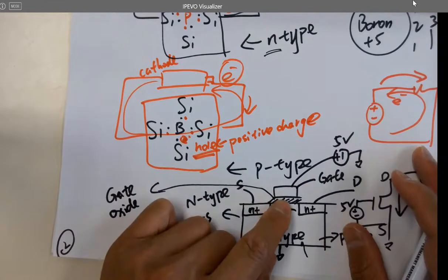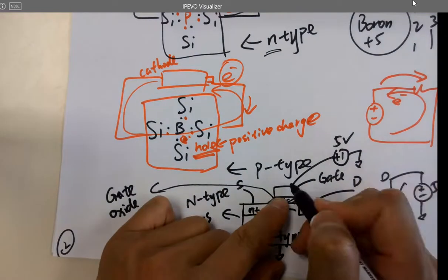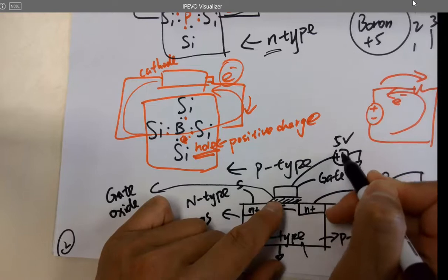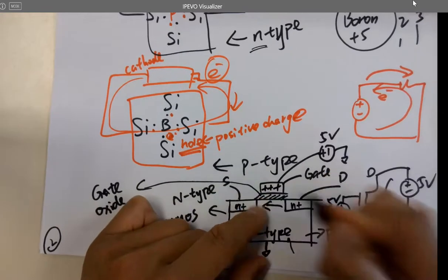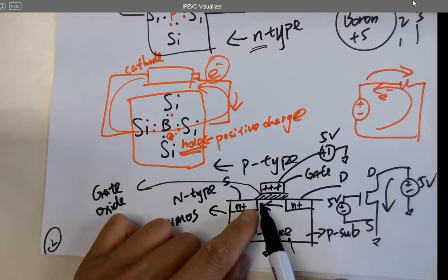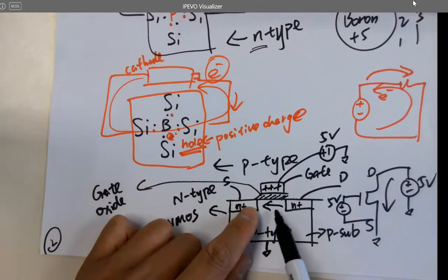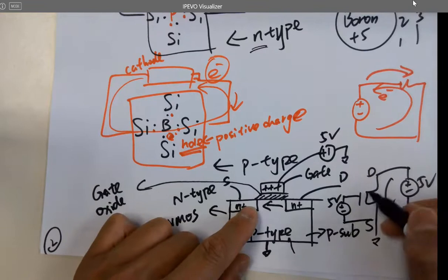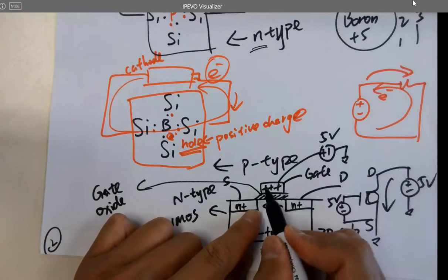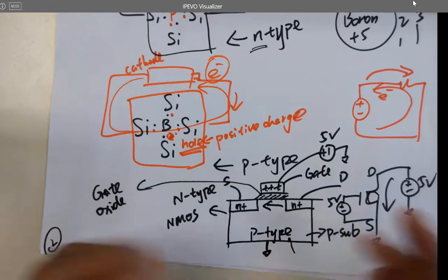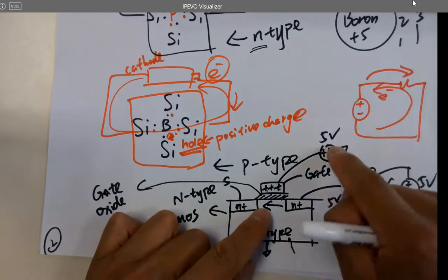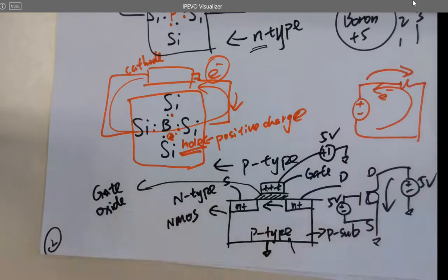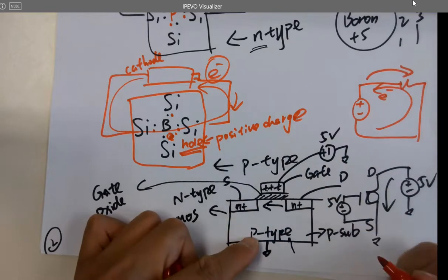It's a dielectric material, but however, whenever you apply a positive charge, which is a positive potential, like 5 volts, what are these potentials in the channel? So this is like a channel here, right? If you have a positive charge through a dielectric material like a cap, so that positive voltage is going to attract electrons from where?